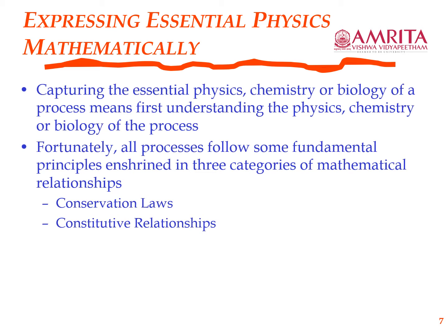The mechanism, the essential physics, is one of conduction, and there is a law called Fourier's law of conduction, and that is a constitutive relationship that relates the rate of a process, which is energy transport, to a driving force for that process, which is the temperature gradient across that solid, and it captures the resistance offered by that solid to this transport of heat, which is captured in the parameter thermal conductivity. And this relationship is a constitutive relationship.